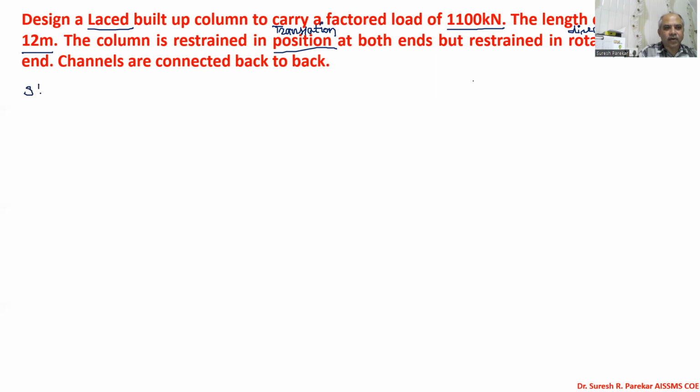So step one, given data. We have given P, that is factored load 1100 kilonewton, so 1100 into 10 raised to 3 Newton. Then L is given 12,000 millimeters. Now the condition: we have restrained in position at both ends,